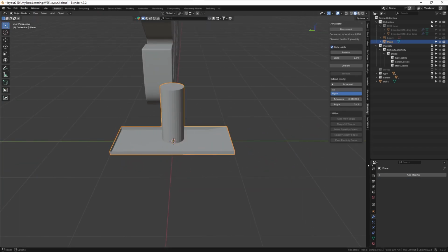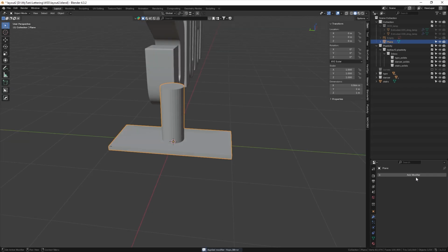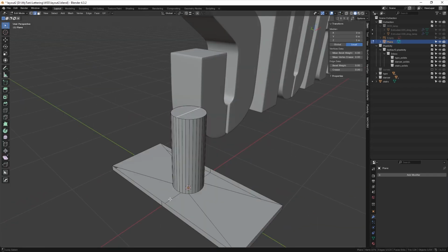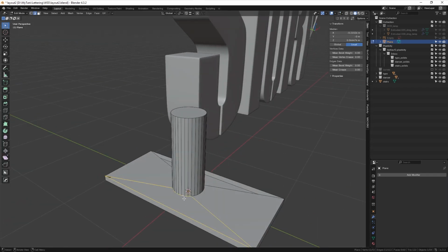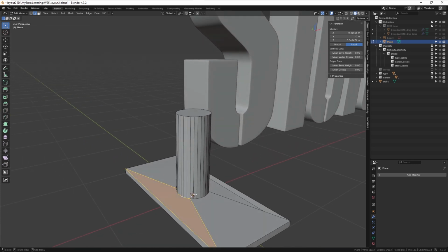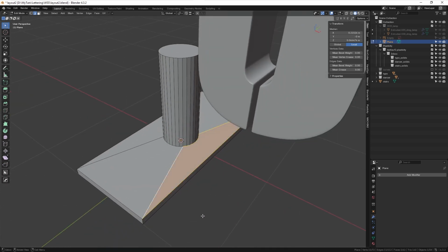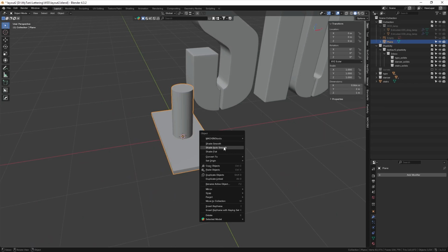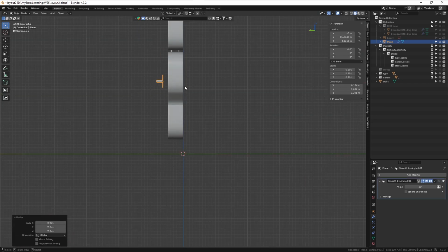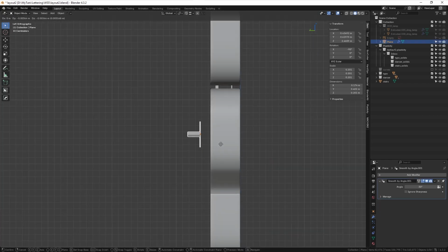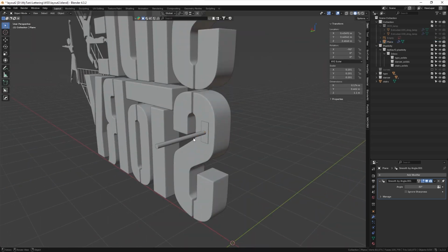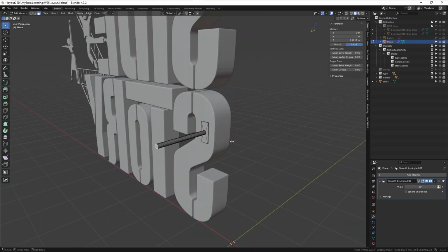Boom. You can do it with the mirror modifier. Apply it and delete these redundant edges. In edge mode, Alt, select this edge loop, F, here also, F. Now we can shade smooth. And now we can simply, in edit mode, duplicate this construction thing.